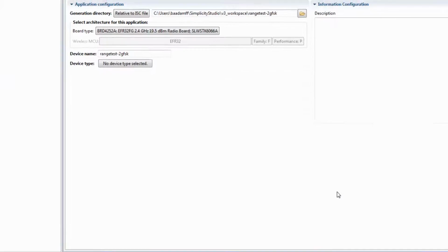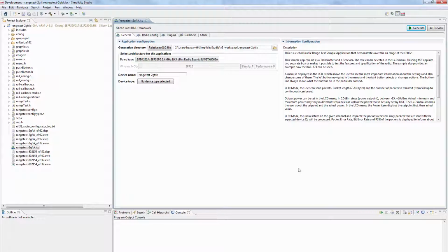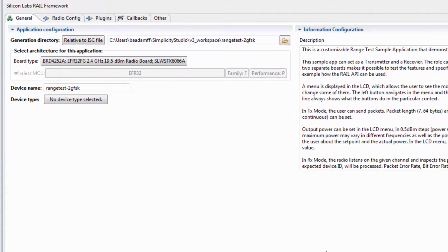When you finish creating your sample application, an Application Builder General tab opens. In the General tab, if the architecture parameters shown for MCU, radio and board type are not correct for your target device, change them by clicking on one of the configuration buttons and then select the right device from the list. In general, the initial configuration settings for sample applications should be correct.